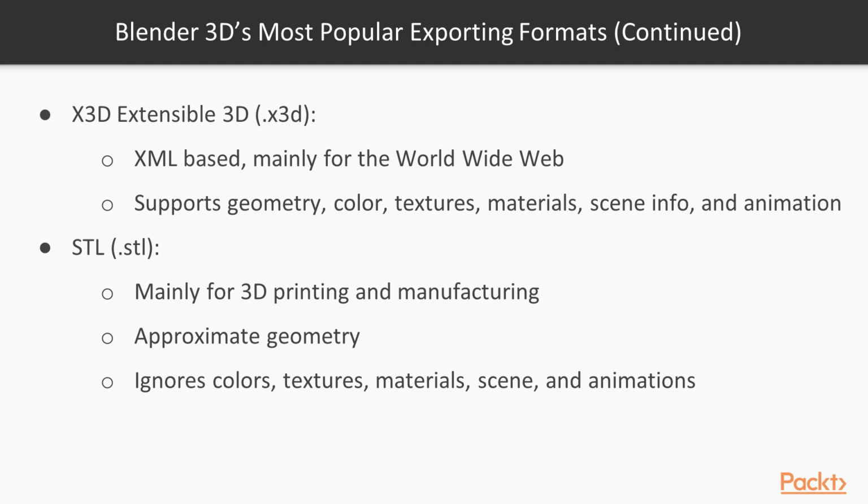Of course, our 3D printers don't go up to, I think it's only like half a millimeter or something, or maybe like 0.3 millimeters of approximation. So it works perfect for 3D printing, and I use the STL file quite a bit for my 3D printer. That's basically what it's for. So when you export your object as an STL, you can pretty much 3D print it as long as it meets the other parameters for 3D printing, which we're not going to get into in this course.